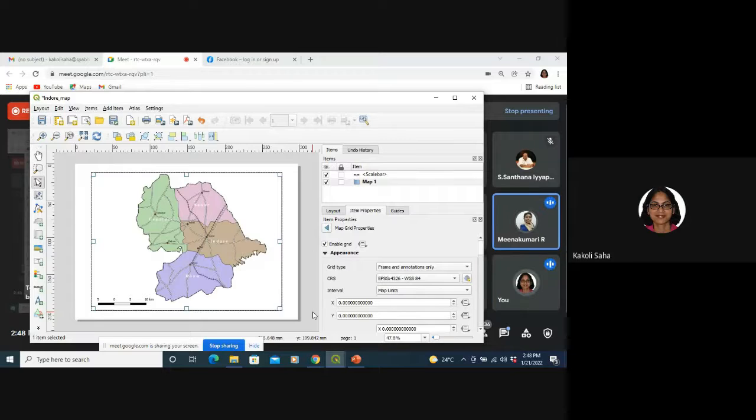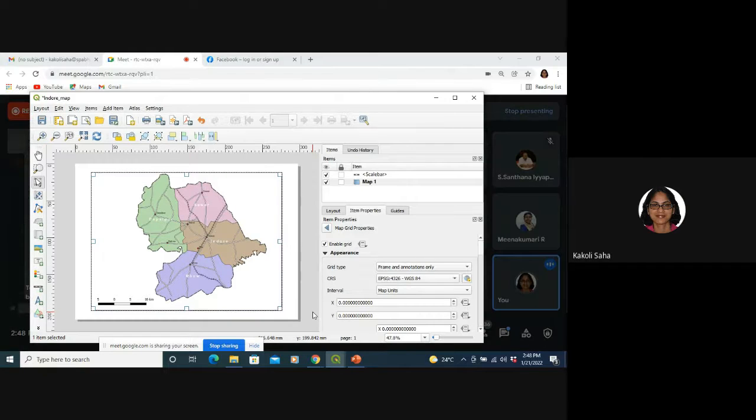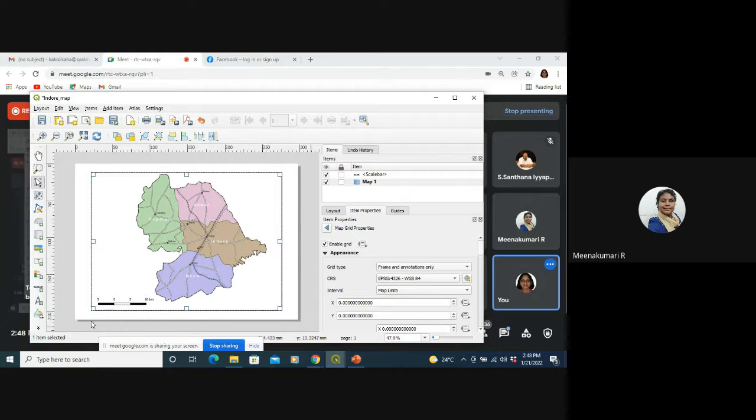We are more familiar with the degree, minute, second system. So that is why I was doing that here. Ma'am, one more doubt. Very good question, and you yourself can try one with WGS and another with a projected coordinate system, that is the UTM, and see what is the difference.